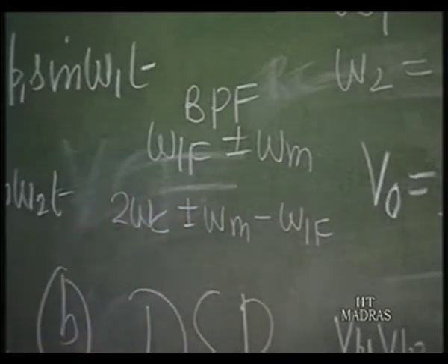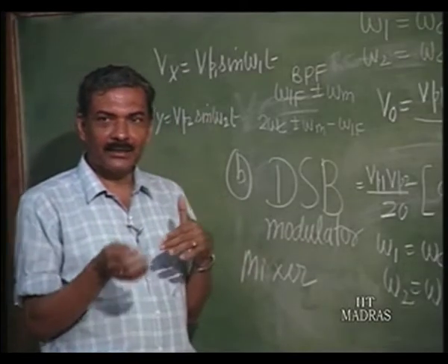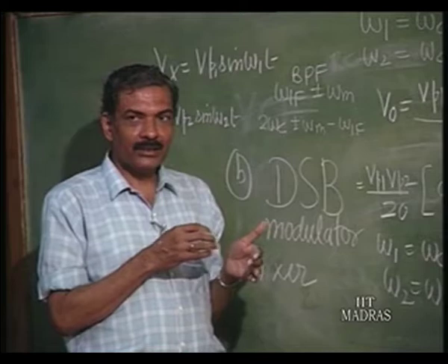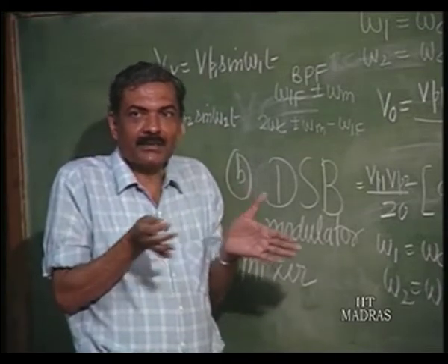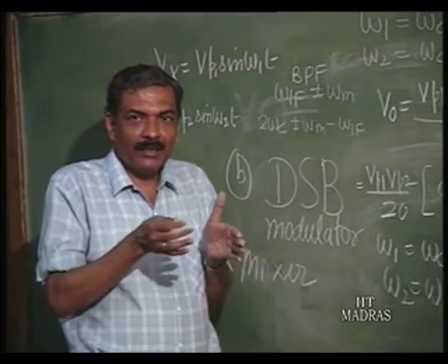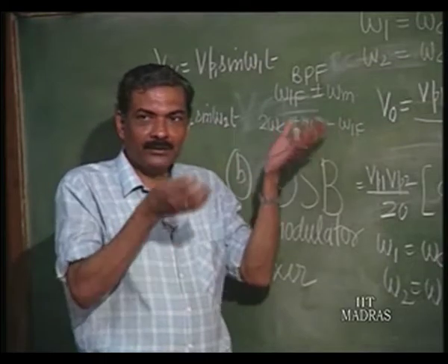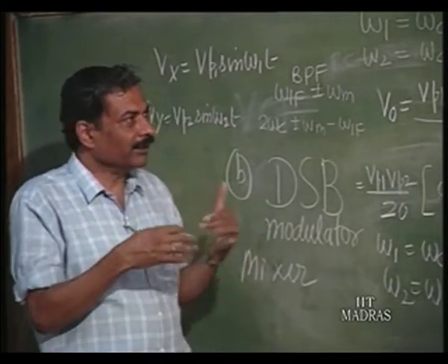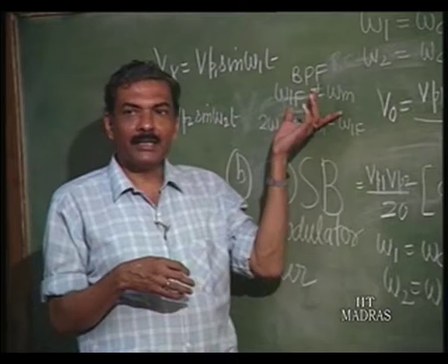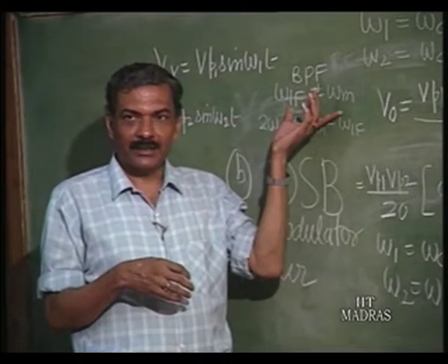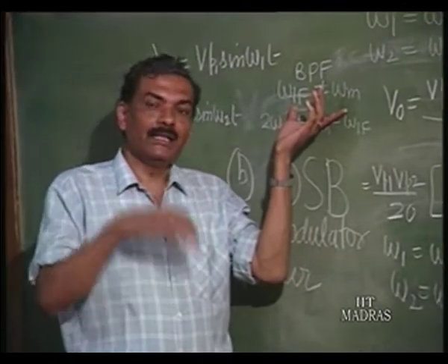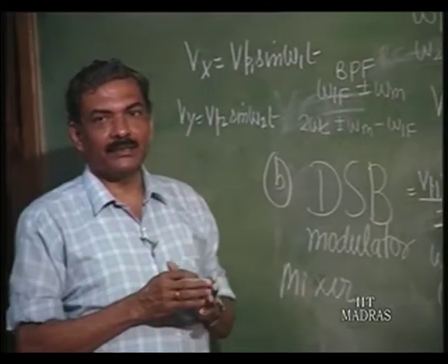This is what is done in both television as well as radio receivers, so that the amplifier design becomes very simplified. Amplifiers that are designed to amplify all the signals have to operate at a fixed frequency, called intermediate frequency, then the amplifier design is very simple.